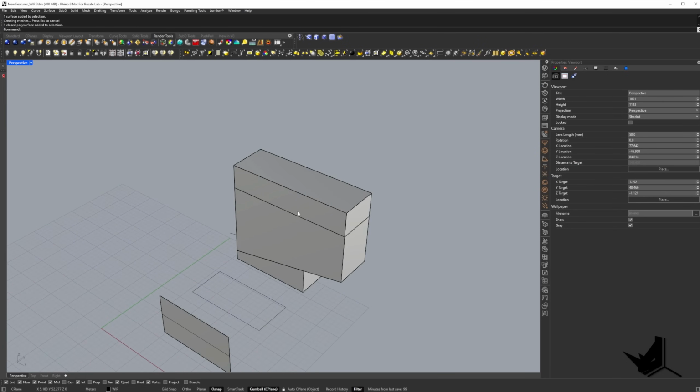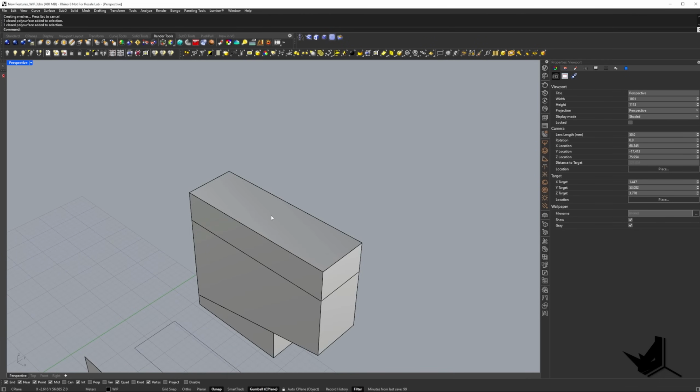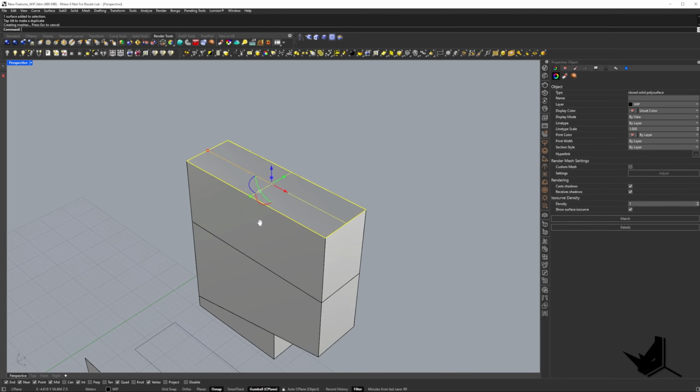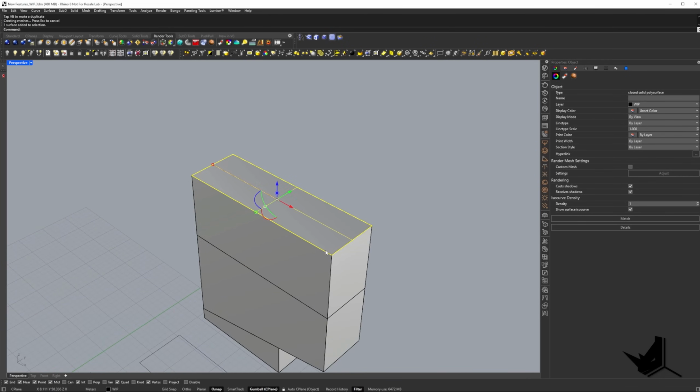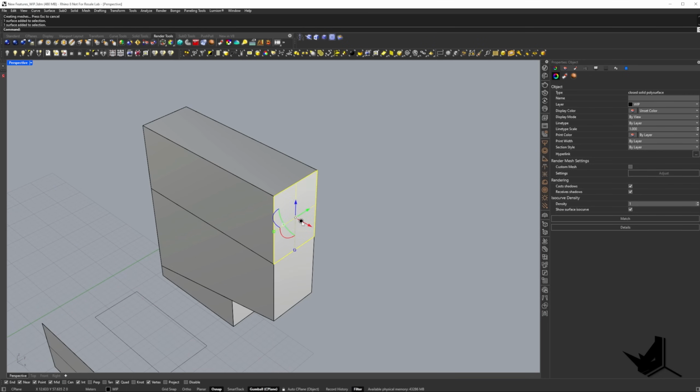However, there is another option I wanted to show you guys, which is a new thing. When you come here to the Gumball and right click on it, you'll have this option that says merge faces after extrude. This can come in handy, of course. If you want to have a seamless model, you can select this, and this means that whenever I do an extrusion now, you will see that it's going to follow. Okay, so whatever option I choose, it's going to give me the same extrusion.